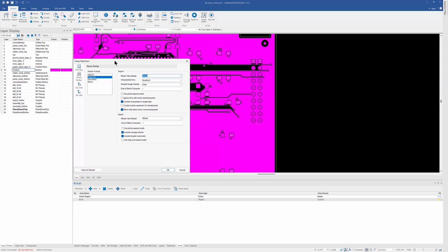So with this release, again, one of these little things has been hanging out for a while. We put this option in here right now. Now, personally, I think it should be defaulted off, but I lost that paddle. But if you want to see the data mirrored, check that box so that anything that has the mirror tag in the Gerber file itself will be mirrored. Of course, that would screw up your netlist and all that if you're trying to extract a netlist from the data, but it is available to you. Honestly, I can remember people asking me for this in 2000. So 25 years ago, people were asking for this, and we finally put it in a tool.